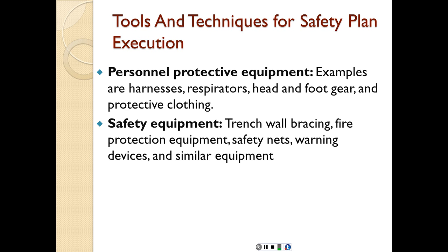Safety equipment such as trench wall bracing to protect it from caving in, fire protection equipment, whether it's fire extinguishers or anything like that, safety nets to protect against falls, warning devices, and similar equipment. Warning devices could be either barricades or cones or even the sirens on the equipment when it's working in reverse to warn everyone behind them that they're getting closer to these individuals.